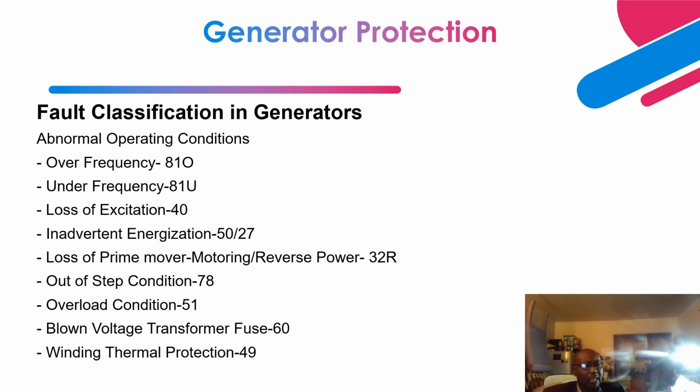If you have a generator that loses synchronism due to a fault that is not isolated as much as possible, then that generator is going to slip a pole, as they call it, and go out of synchronism. Once it goes out of synchronism, the other generators are going to mimic its behavior, and it can lead to a cascading and widespread power loss.